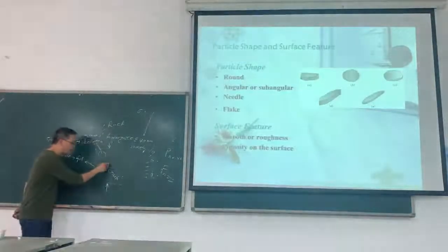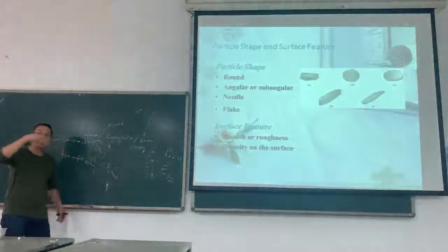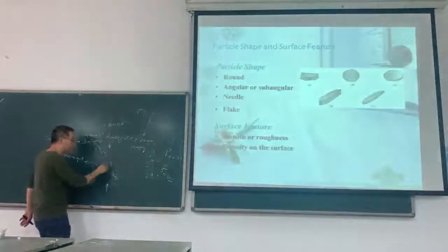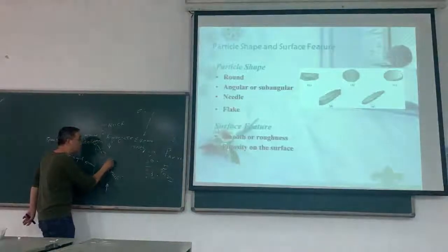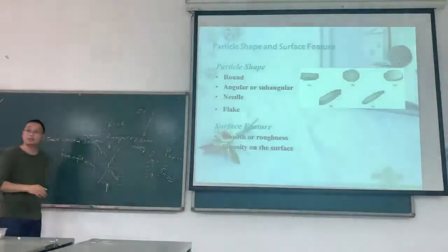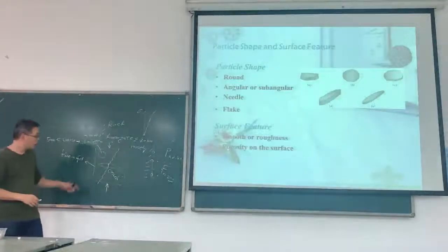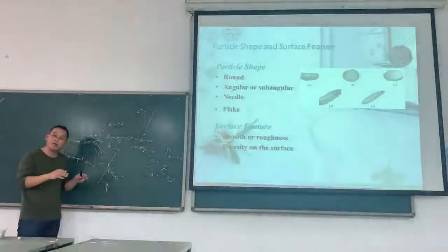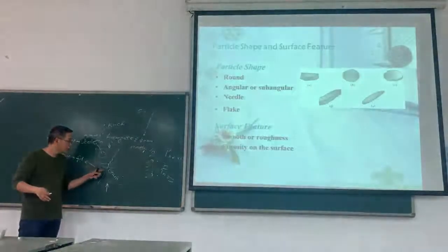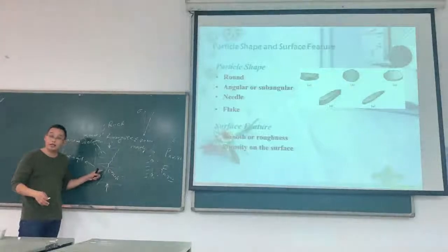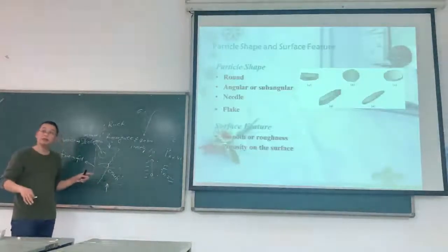Yeah, cracks occur. And then when we increase the load, the crack will develop through the specimen. So, if this specimen has a lot of needle shape aggregate, the strength of it is much lower.